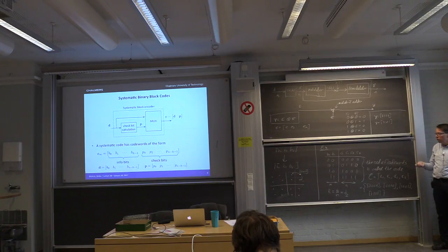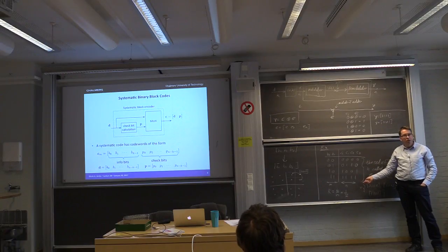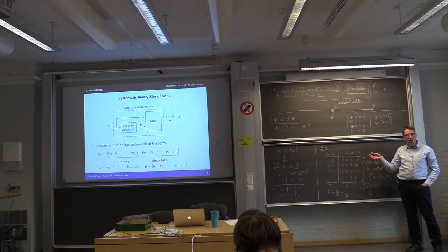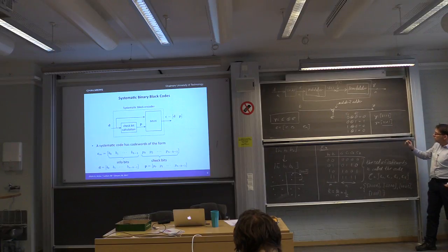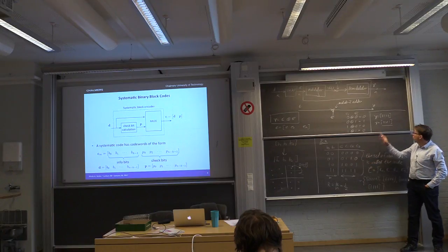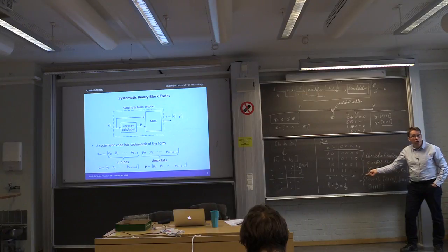And what is our knowledge? Our knowledge is that code words are being transmitted, which means that not all possible bit patterns are transmitted here. We're transmitting 4 bits, but only 4 patterns, which means there are many patterns that we never send. So to check whether an error has occurred or not, one can look at the bit pattern here, 1101, and then go in and ask: can we find a code word which corresponds to 1101? No, there is no such code word, right?